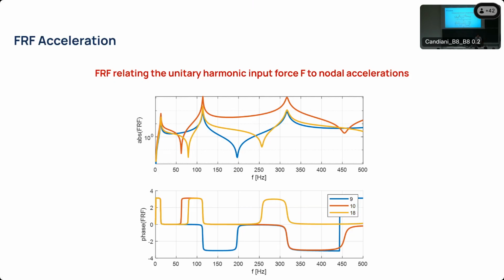If I can give you a small hint, if you want to play a little bit with it, if you already know what the various mode shapes of a beam will be, you can try to see what the frequency response function is on different points of the beam and compare this to the mode shapes and the natural frequencies of a beam.